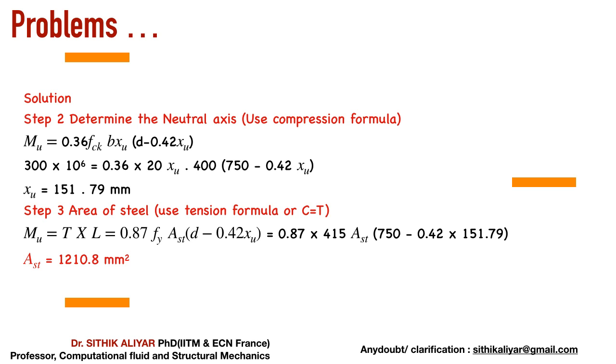Okay, I hope it is very simple. First, step 1, determine whether it is under reinforced or over reinforced. Determine the neutral axis, put it in the formula, and you will get the Ast required. So you can pause it and understand this problem.